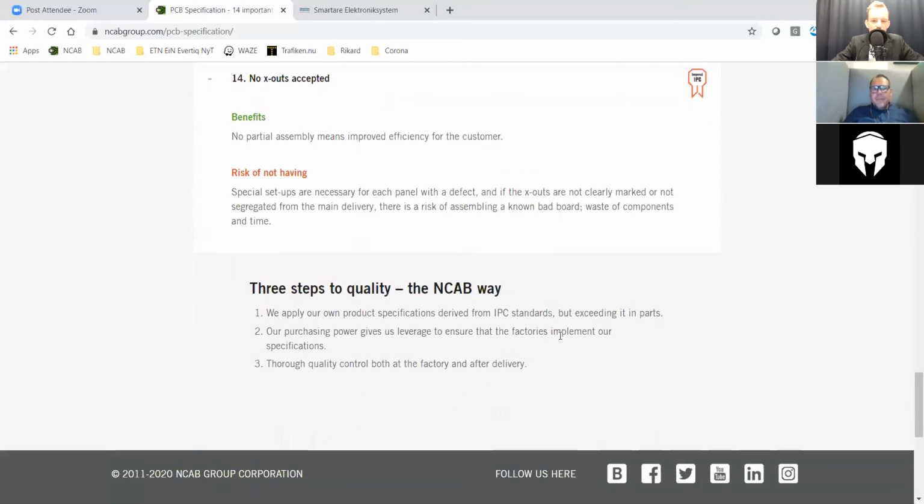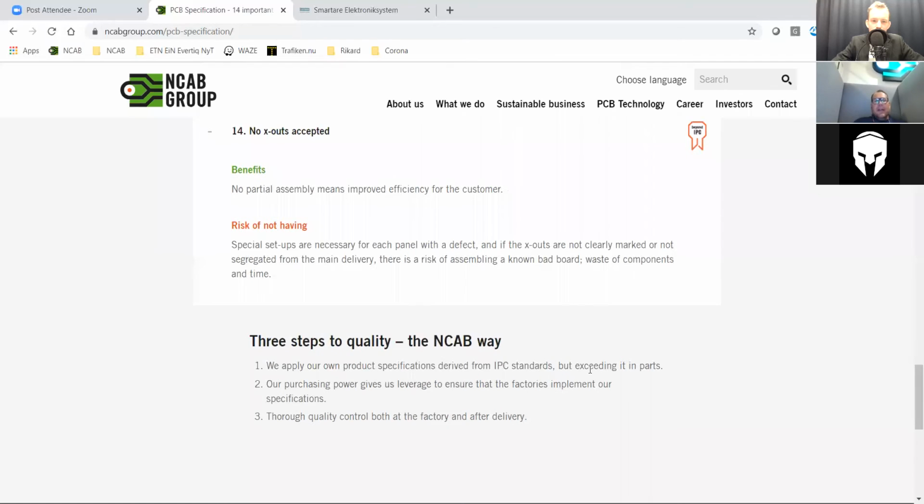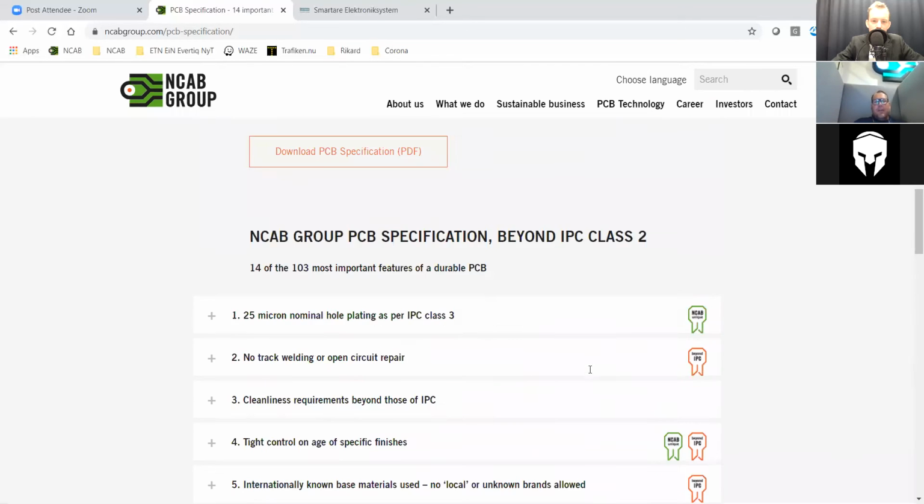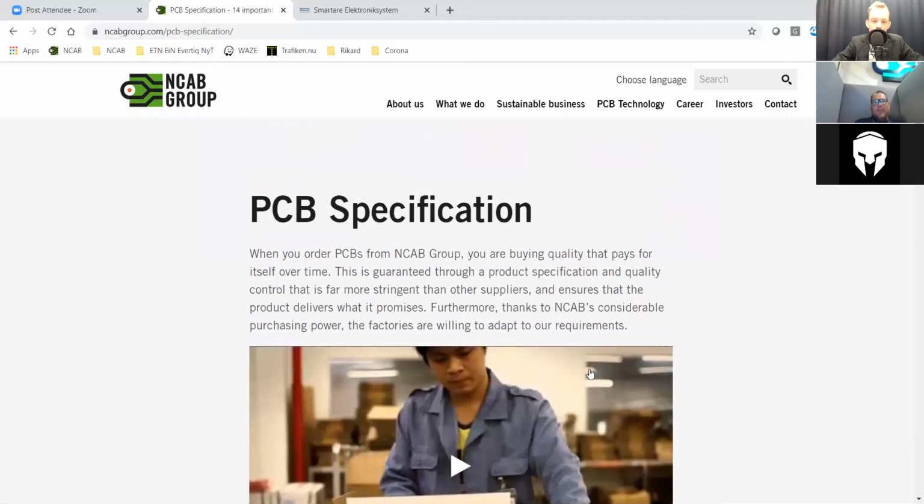Right. So at what point in the design process do you think somebody should contact a manufacturing consultant? Already from the start, I would say. The cost of a PCB is decided when you design it. When you're ready with your design, the purchaser or the EMS partner can always tweak the price, but you only tweak it maybe a couple of percent, because the technology is actually controlling the price. What material have you chosen? What type of build-up? What type of sizes, etc.